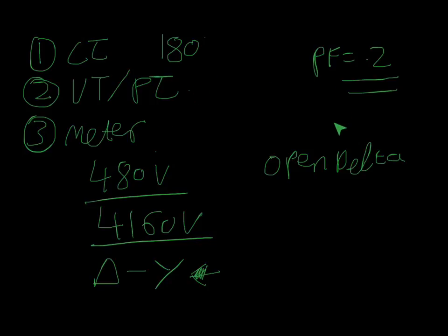And if it isn't, if you have a power factor of 0.8 or 0.7 and it actually is your system, then you're going to want to look at power factor correction units. Cooper sells some pretty good ones, and that requires a design engineer, and you need to get the right specs. Obviously it might be a little bit costly to get that installed, but if your system needs it and you're getting dinged by the utility, then that's what you're going to have to go with.